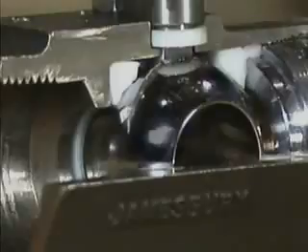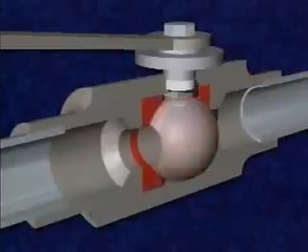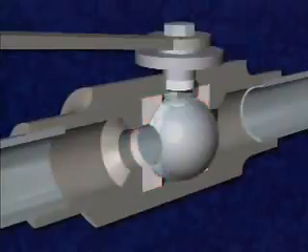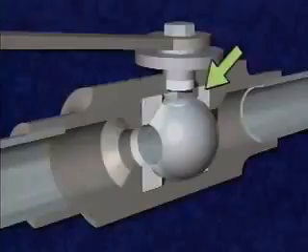The ball is highly polished and its surface is smooth and uniform. A ball valve's disc fits snugly into a ring-shaped two-part seat. The two parts of the seat are called wipers. They're usually made of nylon or another elastic self-sealing material that prevents leakage. One wiper fits on the inlet side of the body, and the other fits on the outlet side.